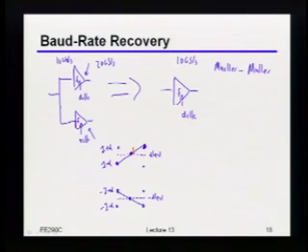Okay, turns out again, there are actually ways you can do this even if you don't necessarily loop unroll. But the loop unrolling is kind of nice because it makes it more obvious why there really is a slope on the data during that period of time. But even without loop unrolling, you may still have slope on that transition at the sample position. So in general, what you're doing is looking for the point at which you're getting the right timing based upon that slope. Okay? Does this make sense to people, or?